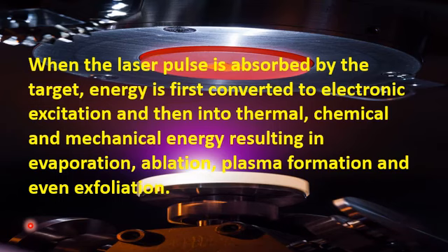So due to this, the source material will get evaporated and ablated and transported onto the surface of the substrate from the precursor material. So let's make it quite simple. In laser ablation, initially a high energy laser falls on the surface of the target material, and it will penetrate inside the target material, but this will depend on the energy of the incident laser and also the refractive index of the target material.